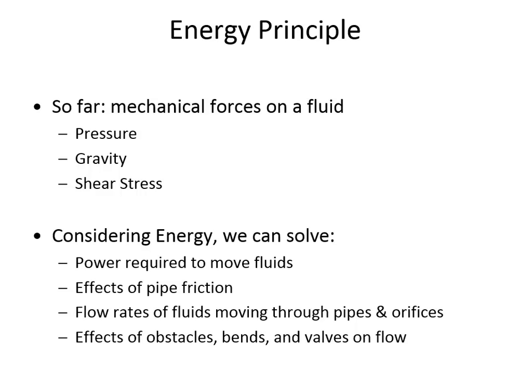But when we allow ourselves to acknowledge the fact that energy is lost as flow goes through a pipe by considering the energy equation, then that opens up calculations like how much power is required to move fluids from place to place, what the flow rates will be when the situation is unregulated and there's just a pipe connecting 2 reservoirs and no pump between them. We can calculate what the flow rate will be between the 2 reservoirs. And also we can calculate minor losses or energy losses that are due to bends, valves, elbows in pipes.